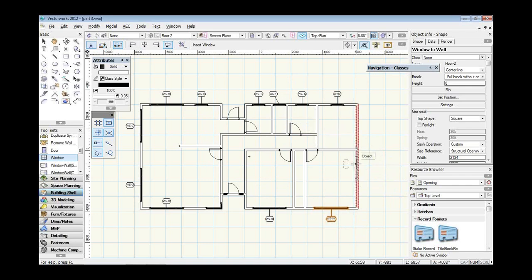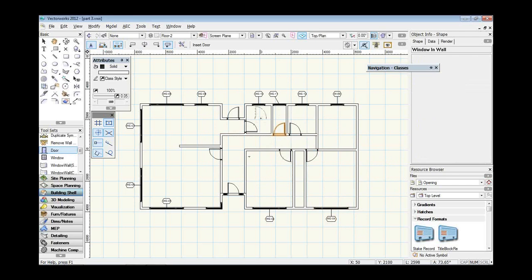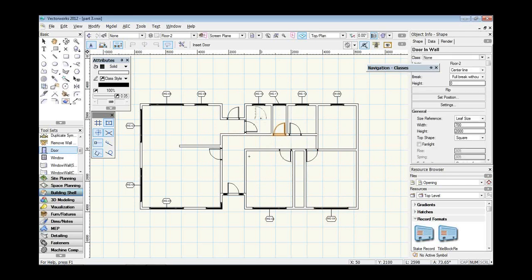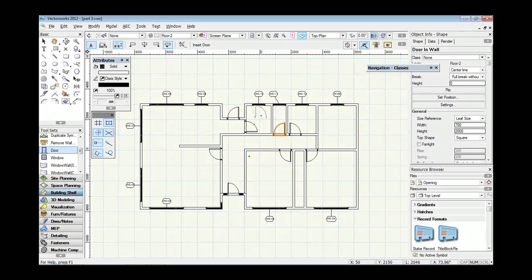Now this technique of the create similar object makes it really quick. If I go near a door, it actually picks up the door information, or the door tool, and it's a copy of the door that I clicked on. This create similar object allows you to create doors, windows, walls, using exactly the same class, the same wall style, and so on. It is a really quick technique for speeding up working in a file.